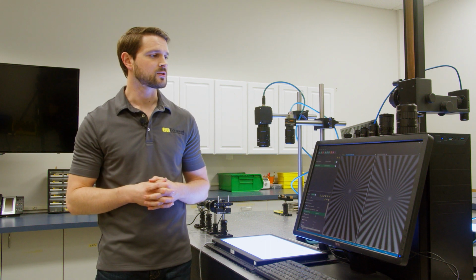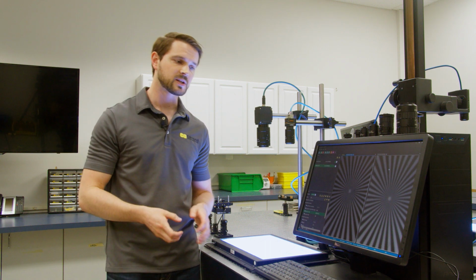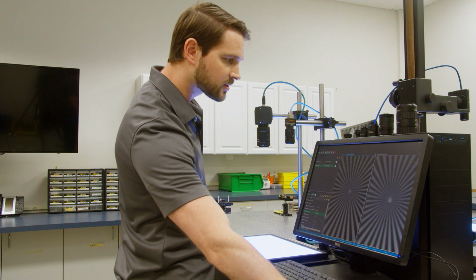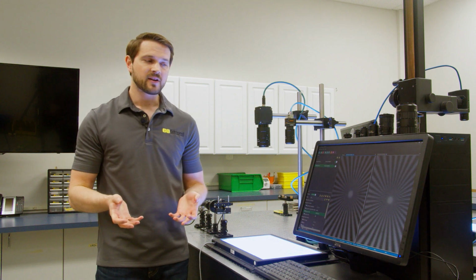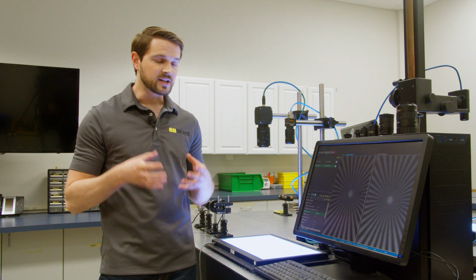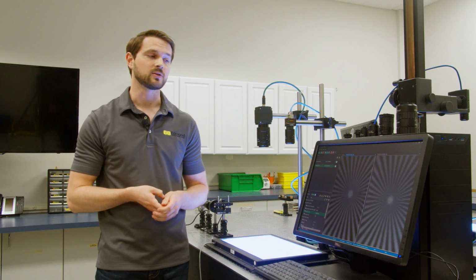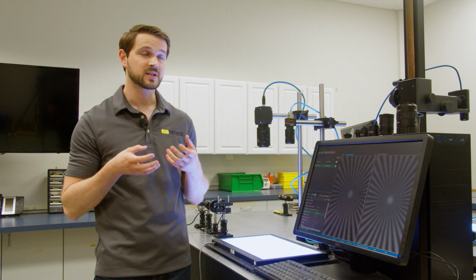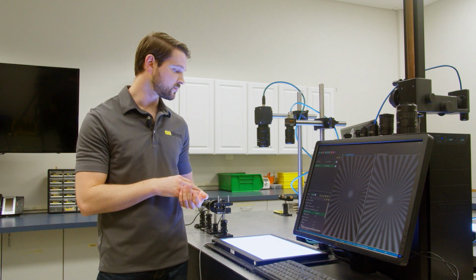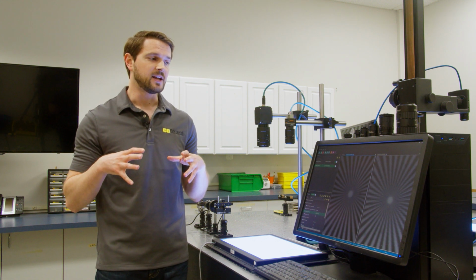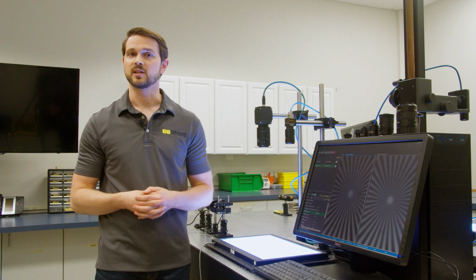In this particular case, the 32 megapixel imager has a much sharper image, and even as we zoom in a little bit farther, really close to that center, maybe one more out here, we can really start to see that taking effect. The higher magnification is just providing a much better and more crisp image. So, quick takeaway from this: don't necessarily think that just because you want to increase your megapixel count you should go to a smaller pixel. Smaller pixels could present all kinds of other issues with this particular setup, and overall, staying with larger pixels is going to give you better image quality.